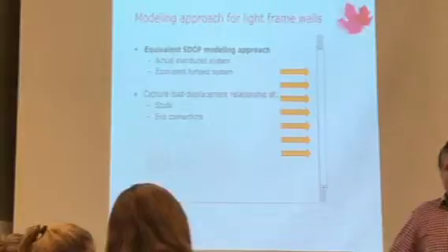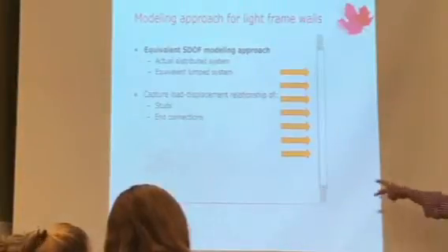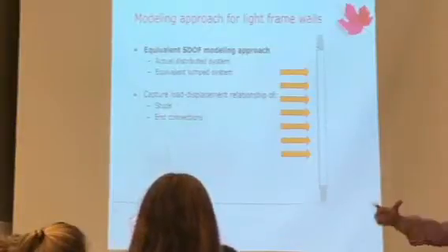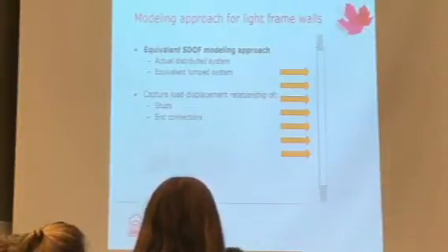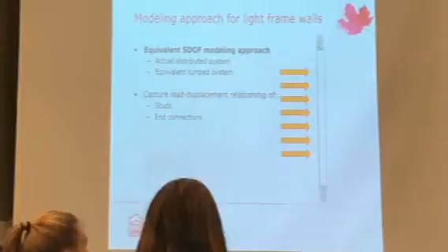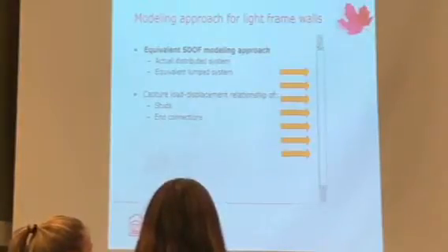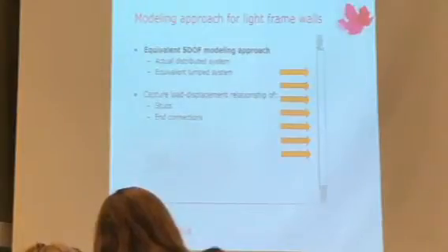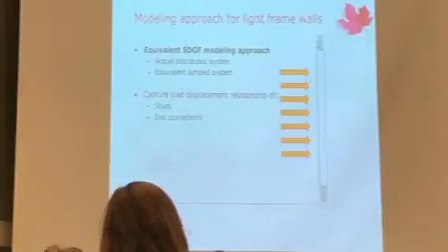For example, what I'm trying to do here is take a beam, and I want to simplify my analysis, right? The beam has a mass, the beam has a stiffness. Surely I can do this. So how do I do this? How can I go from a distributed mass, distributed stiffness, distributed load into a single degree of freedom? Anybody have a clue?